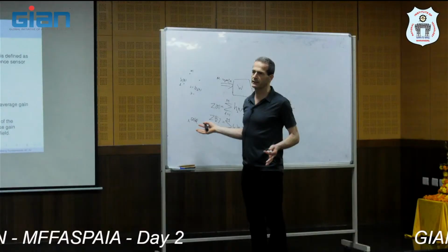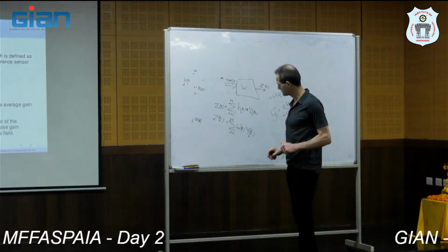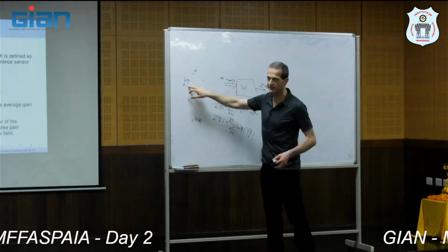After the output, suppose that I have certain weights or certain filters. I get output here, and because it's linear, this is a linear beamformer. It means that we have some weights or some filters, and it's the same in the frequency domain. Here we get some output SNR. We can write the output as a summation of two components, one desired, one undesired. The power of the desired compared to the power of the desired in one of the sensors has some ratio.